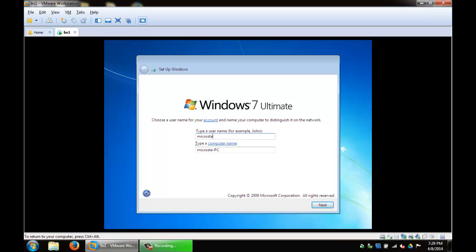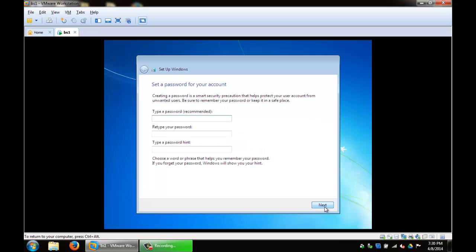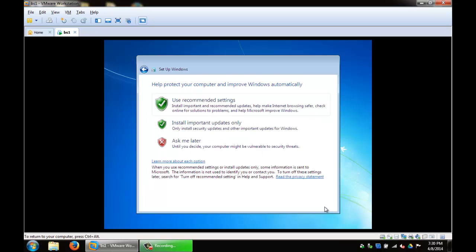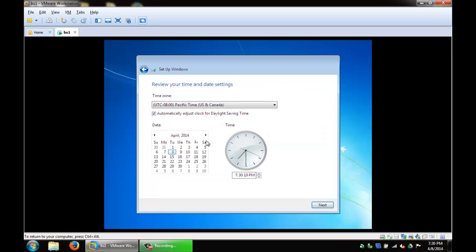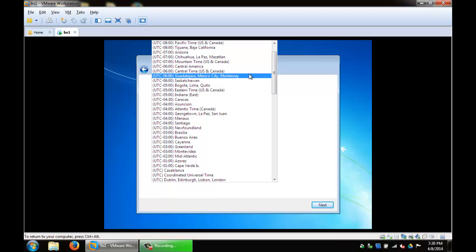I would also take this time to typically go ahead and install the users in Active Directory if you are using a domain and domain controller. In our particular application, our domain controller, Active Directory listing, and local Bentley Select server are all hosted on the same server. This makes it very easy for us to administrate it, and I have 3 users assigned: MicroStation 1, MicroStation 2, and MicroStation 3 that correspond with the 3 different license keys.